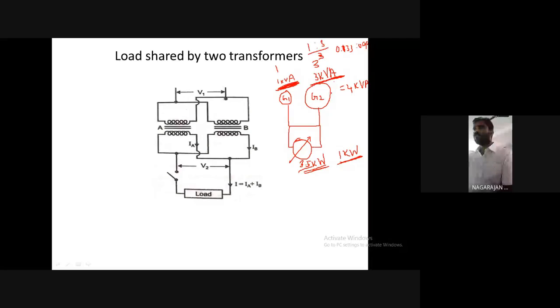What will happen now is, we can save a lot of energy. For example, when 3 kVA total power is given, current will be very high, obviously, when the load is measured in terms of current. When full load is given, the current value will be high. So what will be happening to the I square R loss? During full load condition, what will happen to I square R loss? Can anyone answer? What do you mean by full load condition? The entire capacity of the machine is met at that condition. That is called full load condition.